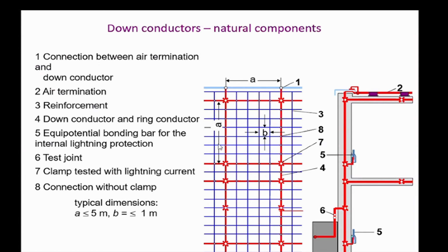And some people, as they find it a little difficult to practically fulfill those three conditions, recommend having a mesh of additional tapes, maybe copper tapes, maybe aluminum tapes, maybe some other type of tapes, GI tapes, connected to the steel reinforcement bar.